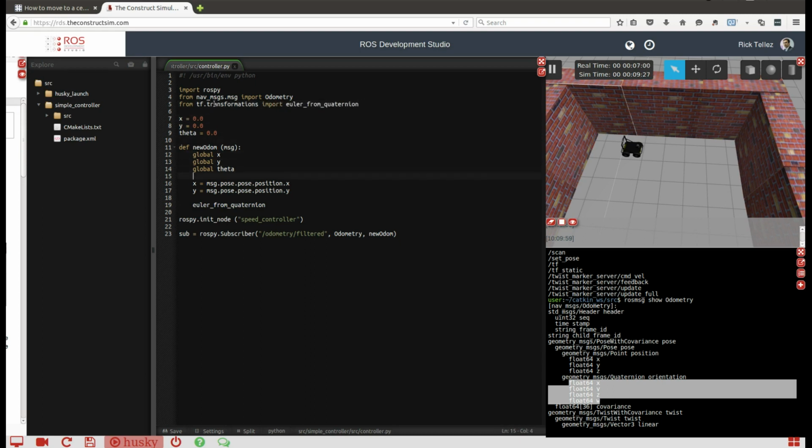Great. Now let's call it. The euler_from_quaternion will provide us with 3 different angles: the roll, the pitch, and the yaw. It provides them in this format: roll, pitch, and the yaw is exactly the rotation in the z angle. So we can specify here directly theta.